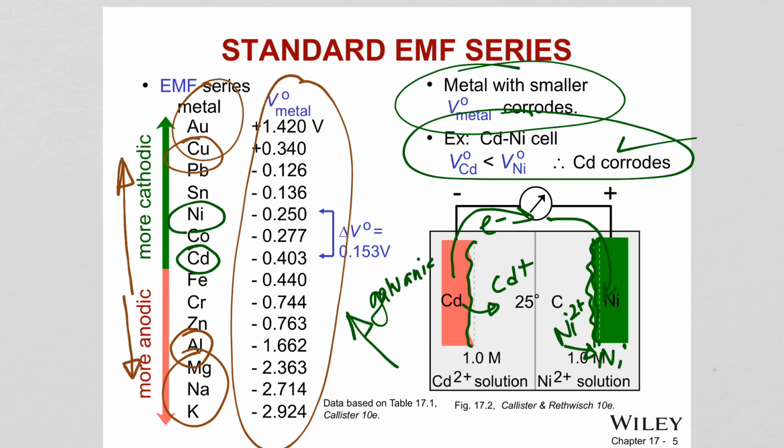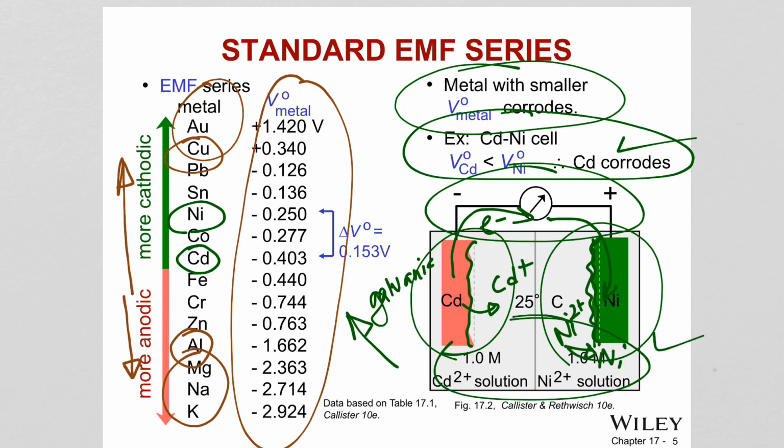When you connect two different metals electrically in a liquid, you see there is the electrical connection here, so electrons can be transferred. There is the electrolyte that carries the ions, and there is the anode and the cathode. All these present together make the corrosion possible.